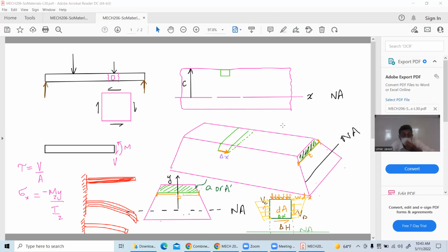Okay, so now that you are convinced, this is a little chunk that I took. For students who are saying, why this chunk? What I'm saying is, do you see this little layer? Let's say I have glued this with this big chunk, or I have pinned it with this chunk. So technically this glue or this pin can shear. Now when I'm putting a load from the top, I know that this whole thing will bend and I will have what is known as bending stresses, right? So right now I am taking an element from here.